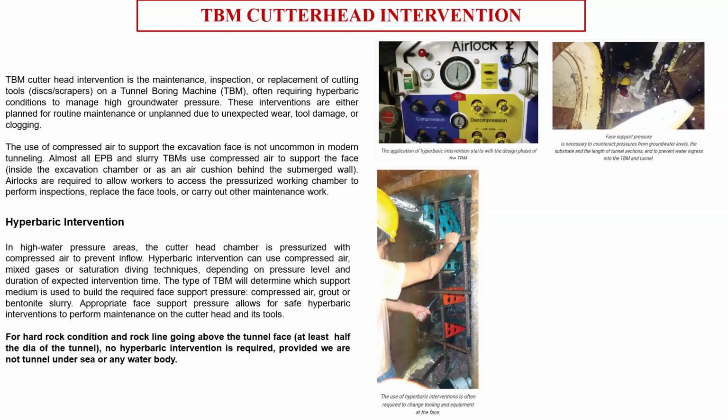So, sir, is that extra excavated part filled just after the casting of the segment, or is it left? After casting of the segment, we fill it with grout or pea gravel. That filling is the primary grouting we do first. If you are making an over-excavation and the ground is very soft, you will encounter a high volume loss. So the excavation part and the strength of the ground have a very important role in the volume loss.